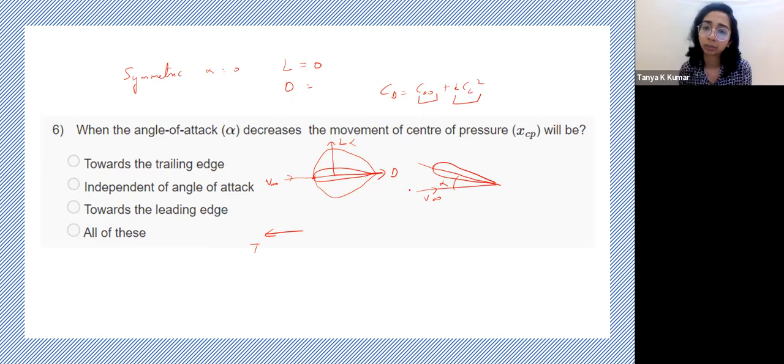So now let's come back to our original question. When I increase the angle of attack, what happens? You were right. You said that at 0 angle of attack, it hits the leading edge first, and the pressure above and below remains the same. There is no effective lift. All that is right. Then when I increase the angle of attack, what happens? Where does the oncoming airflow hit?